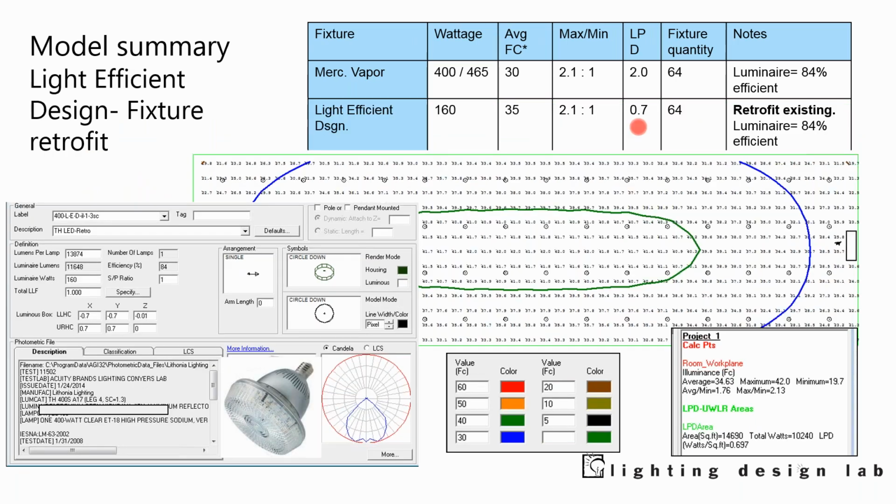So why not just pop the champagne corks and declare victory? But we looked at it and thought maybe they could do better. One thing to keep in mind with this, even though it has a screw-in base, you actually have to go up to the fixture and rewire the fixture. You have to bypass the existing ballast. So this is designed to operate off of line voltage.